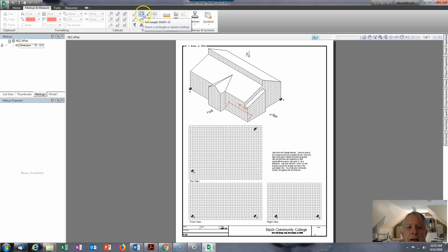Do not use the rectangle or the connected polyline tool for this exercise because you'll probably end up erasing more than you need to. Start instead with the line tool. Make sure to set it to color blue and to a 1.5. And go ahead and draw. You're just sketching. Let's start with a solid line type. So pick from the top, solid line type, and just go ahead and sketch.